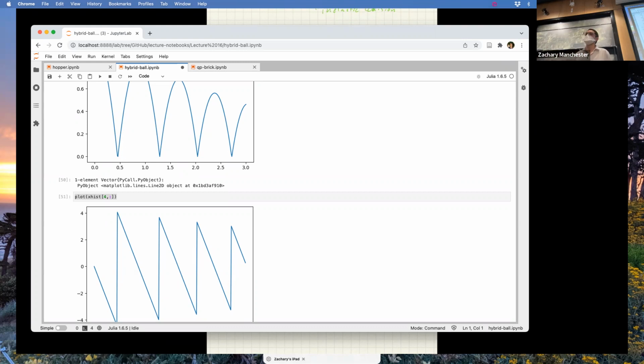Like, I don't know, examples, you could say, I don't want to break my robot. So I don't want to exert gigantic contact forces, or break whatever I'm manipulating, right? There's definitely lots of instances where you might want to do that. And so in that situation, with the contact implicit stuff we talked about before, where those lambdas are explicitly in the problem, I can put whatever constraints I want on them, and it's kind of easy and natural, right? Here, you'd have to actually go and compute those some other way and add constraints on them that way, which you can do, but it's extra work.